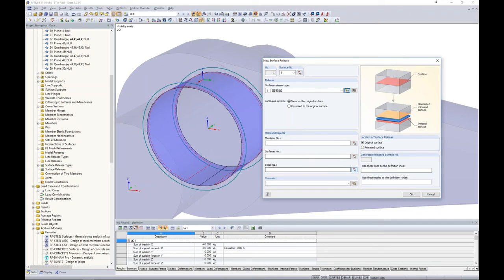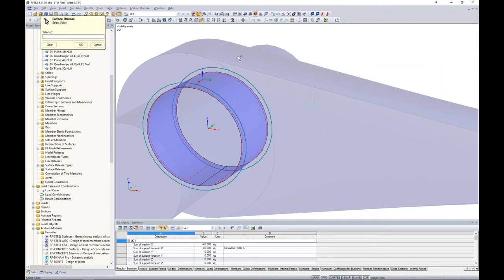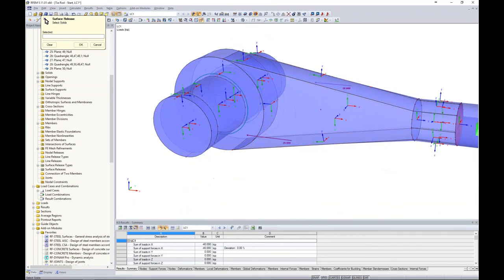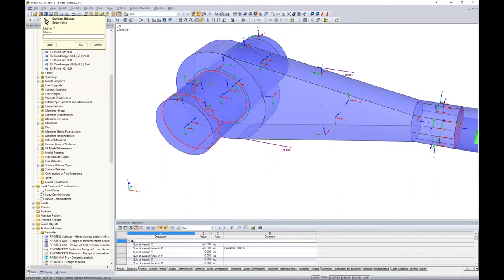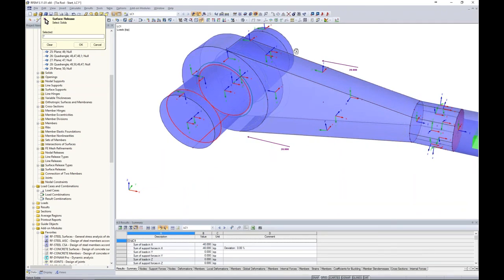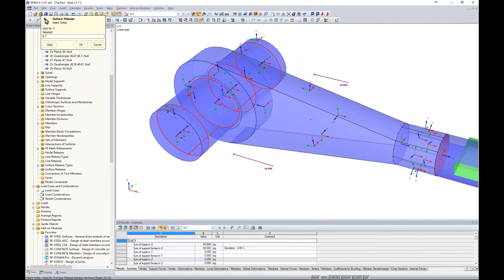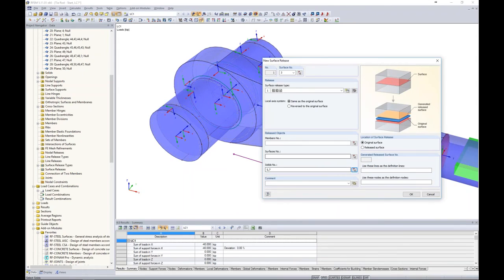Well, this is where I'm going to choose my solid element. We can exit out of this visibility mode, and here I'm going to choose my solid on the left-hand side, which is the left-hand portion of my bolt, as well as the right-hand portion of my bolt. Now, there's also a solid within here too, but you can't easily select it graphically, and that's only because we have an additional solid defined for our ring element. So what I can do is click OK. I only have solids 5 and 7 defined here.